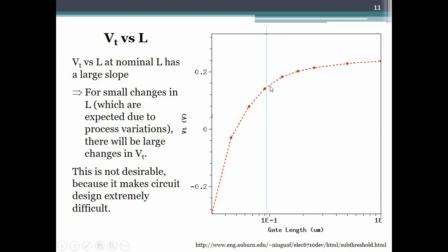Let's say in 180 nanometer technology, there is always small variations due to fabrication uncertainties, so that if you have built 1,000 MOSFETs and you had designed them to be built all at 180 nanometer channel length, when we actually build them, the actual channel length would vary by about 2 to 3 to 4% from this nominal value of 180 nanometers. So these 1,000 MOSFETs would have channel lengths that would vary, let us say, from about 175 nanometers to 185 nanometers or so.